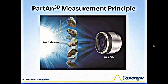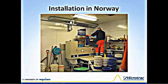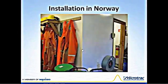This illustrates how the three-dimensional mode of dynamic image analysis works. The digital camera tracks the tumbling, rotating orientations of each particle, and from those multiple individual images calculates maximum and minimum parameters so that all 3 axes are calculated. This is a short video we've been given to use, which illustrates a live measurement being made on a PartAn 3D Maxi at an aggregates plant in Norway.